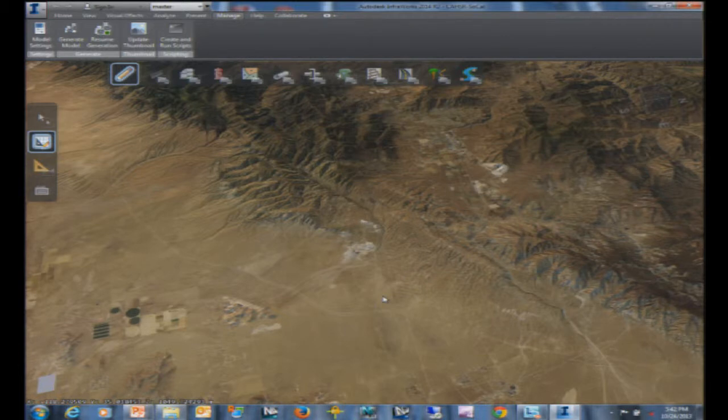Any other questions? Yeah. When you update attributes or update geometry in InfraWorks, do you have to rebuild the model, regenerate the model, or is it done on the fly? Yeah, no, you have the option of hitting regen, because if it has to regenerate something that affects an aerial, it rebuilds the aerial. It's got this complicated tile caching system, which is local.